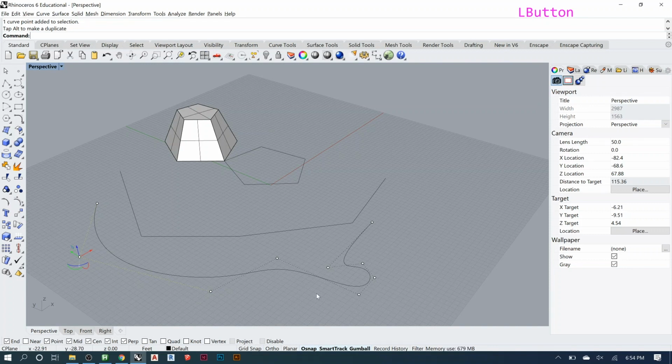So that fundamental change is what allows Rhino to be so good at curved geometry, because now you can start putting areas where you would want the geometry to start getting near, and it can just start to average out those shapes. So you don't get a perfect from here to here is 10 feet, and then it's going to be perfectly 11 feet. You'll get 10 feet all the way up to 11 feet and all in between, depending where you measure from, because it's going to give you those nice smooth curves. So as you're working, you can start to do this and move this like that.